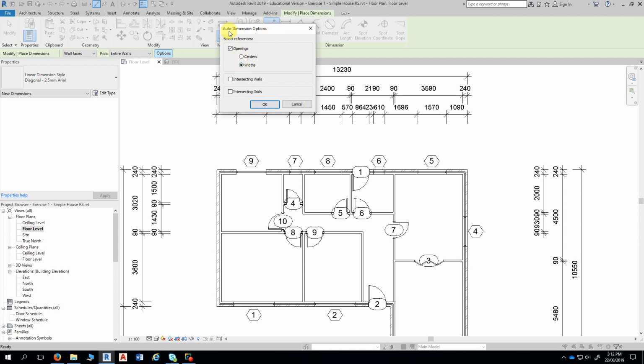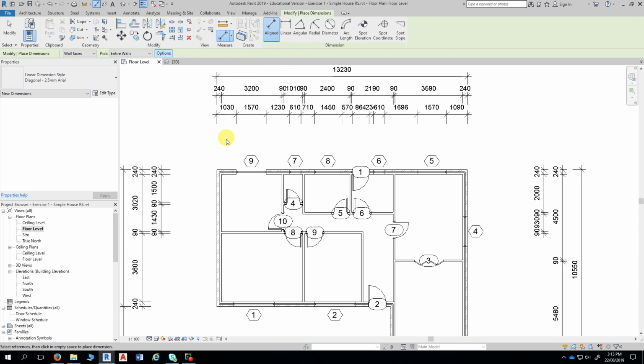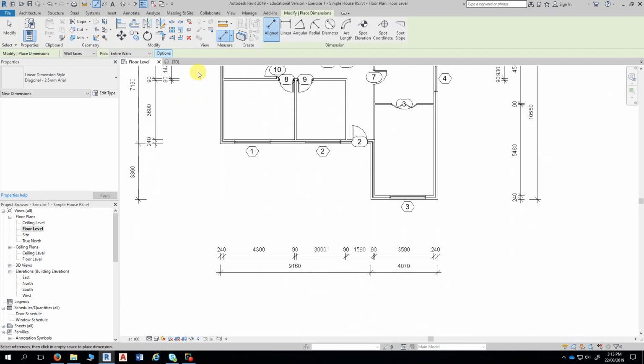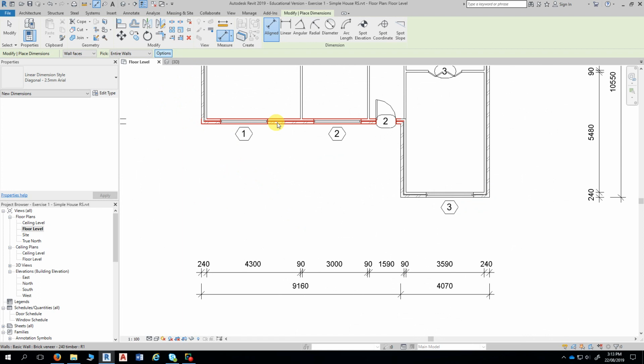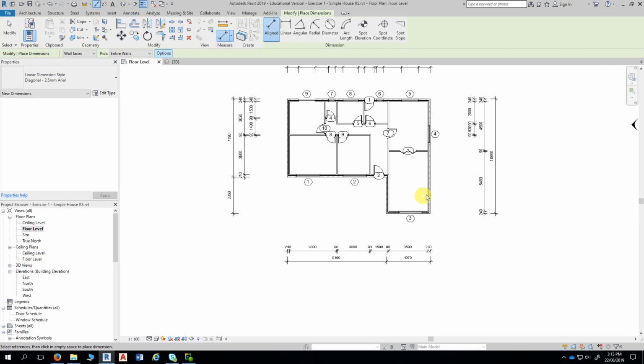Now this is called auto dimensioning, okay? Now it will work on straight walls like this, but when you get a situation like this where that wall then takes a turn and goes down there and across there, it's better to do individual picking in this scenario here, okay? It works better on complete walls like that, so single walls like that, and that.